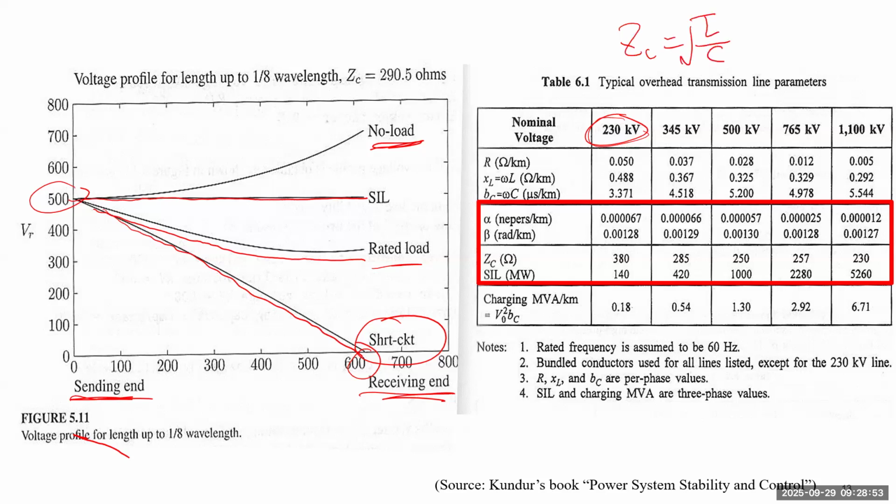It doesn't depend on the length of the line. So you will know the surge impedance, and because you know the voltage, you can calculate the surge impedance load.